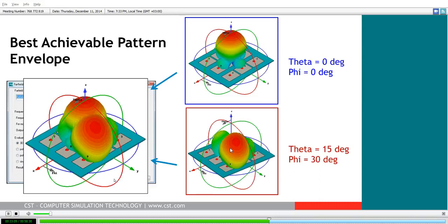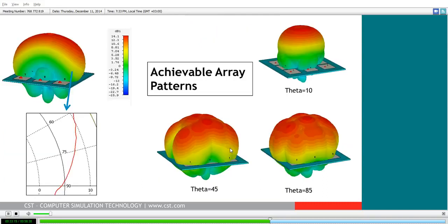And certainly it gives a very nice intuitive level of insight to the array designer in terms of the coverage that they're getting to just visually inspect this and see how their gain really is going to perform over these different angles. So here you can see for a sweep of steering angles what our array performance really looks like. You can see in the top right-hand corner, obviously for shallower steering angles, in this case this is a pattern for theta equals 10, so we're just 10 degrees off boresight, and then the full 360-degree azimuth sweep. So you have the full circular range.